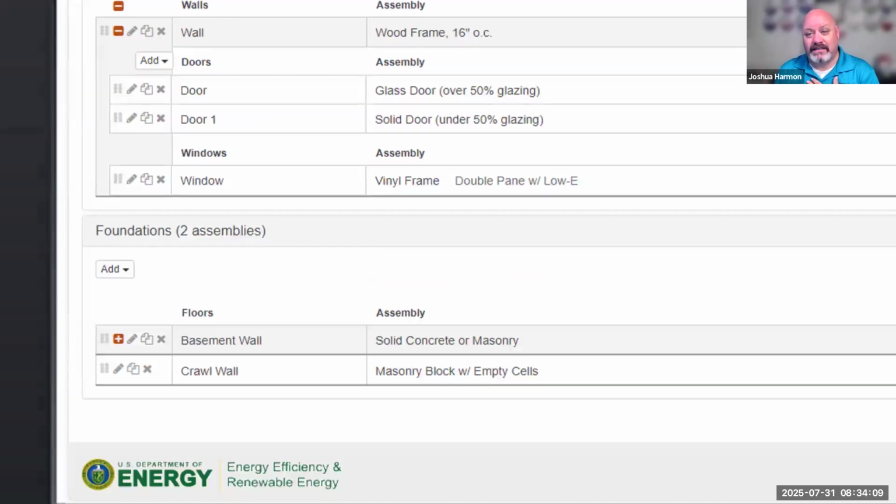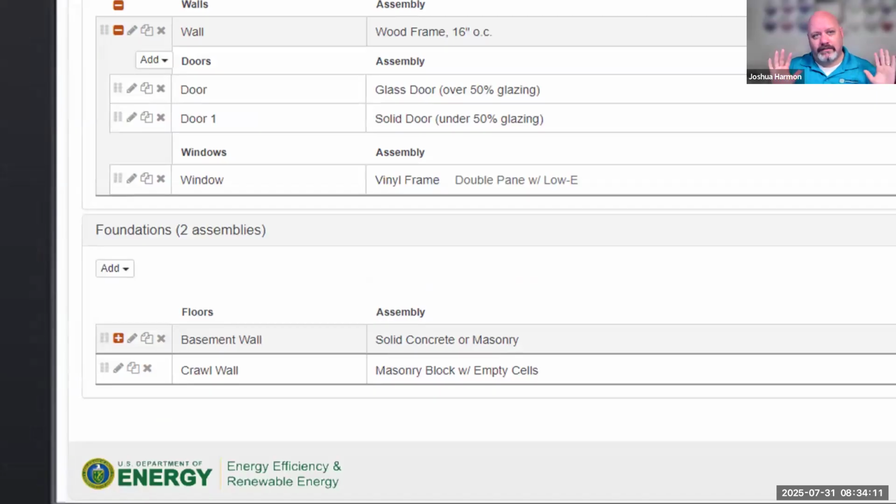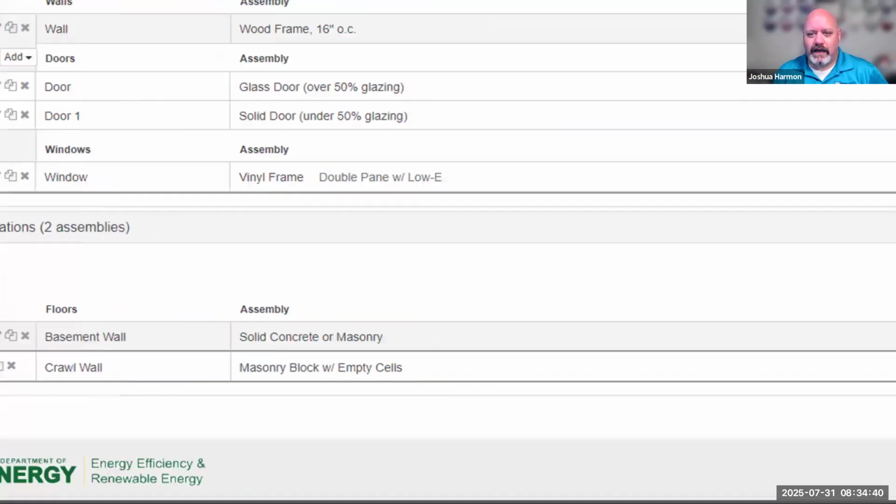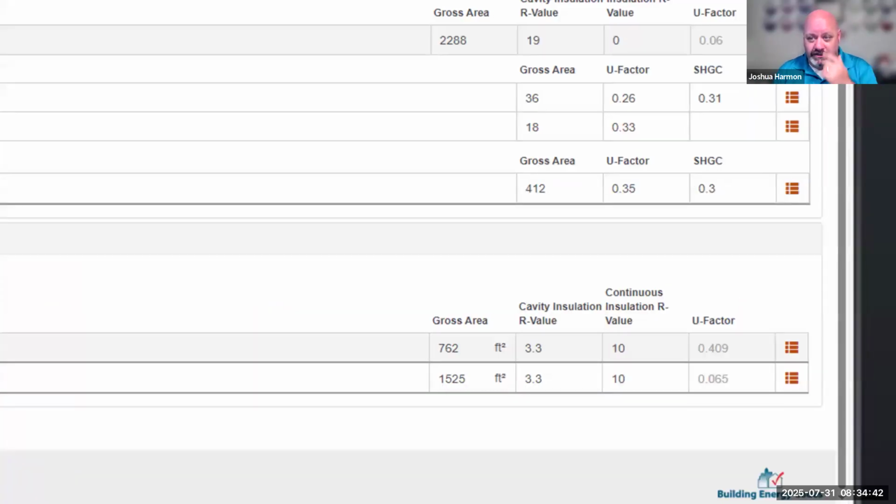I like to have it designed because if I change something, maybe, and again, this is my house, on the north side of the building, we have a thicker drywall and thicker insulation because it faces the road. Whereas on the south side, we don't care about that as much. It's a more rural atmosphere. So I can have different variables. By adding a little bit of insulation here, I can maybe reduce insulation on the other side, trade it off. Again, I've got my basement, I've got my crawl space, the square footages, how deep, and what kind of insulation we're doing on those.